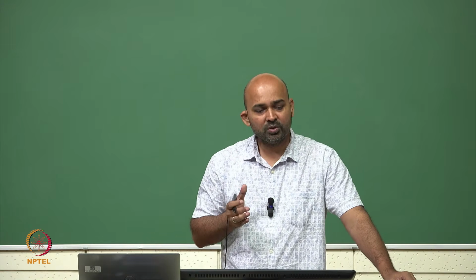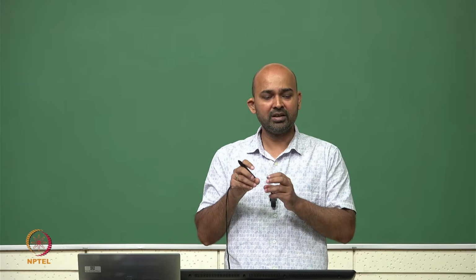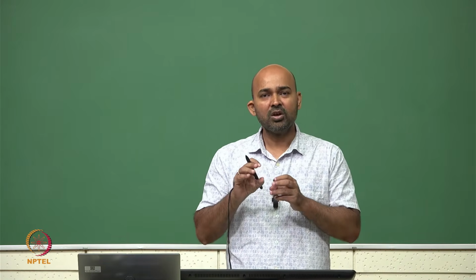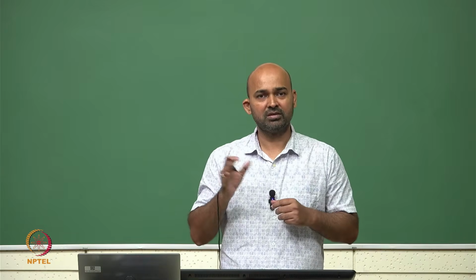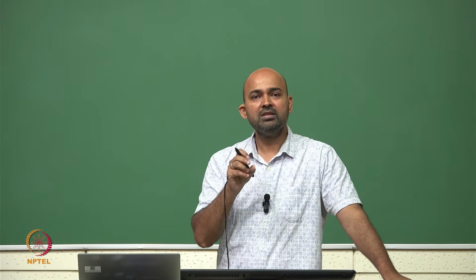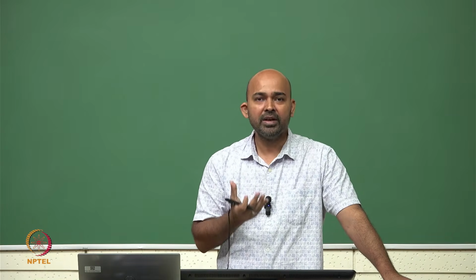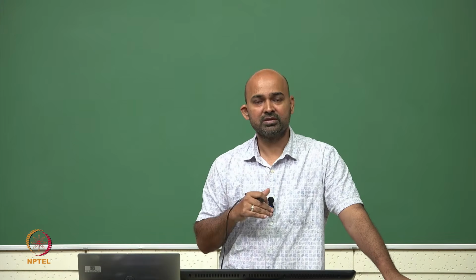So, the first thing we need to discuss is when we make circuits using semiconductor devices, we have diodes and resistors in series and parallel. These semiconductor devices are not linear devices. The characteristics of these devices are exponential or some other quadratic equations. So, when we put these devices in the circuit, we first need to know the operating point of the circuit, then only we can solve for the transient simulations.